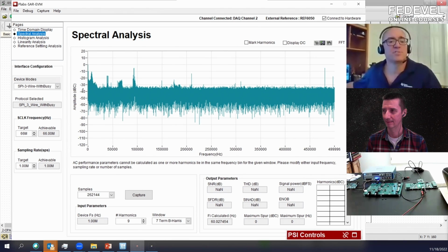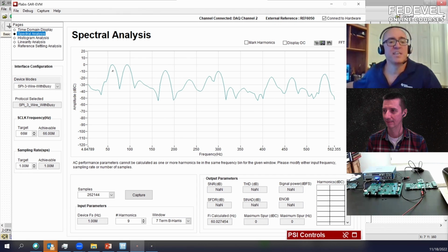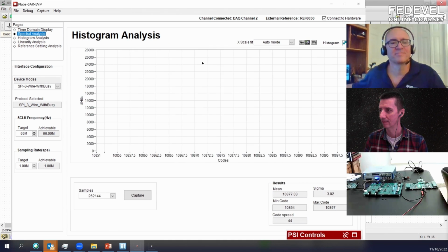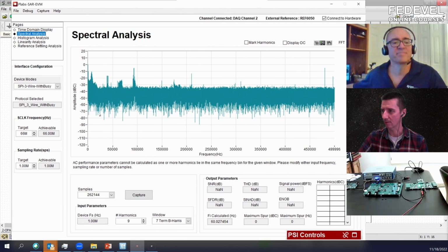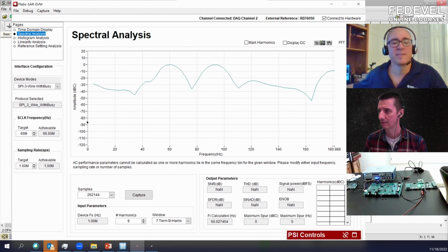And now we can zoom in on this area here, zoom in further, and you can see 60 hertz, 120 hertz, and various harmonics of 60 hertz. And so 60 hertz is a major problem here. Oh, wait. Go back. The first one is 60, but the second one is like 90, no? 60, right. It should be 120. I don't know why it's at 90, to tell you the truth. So we should have harmonics of 60 hertz. Maybe you moved the wires a different way. Yeah.